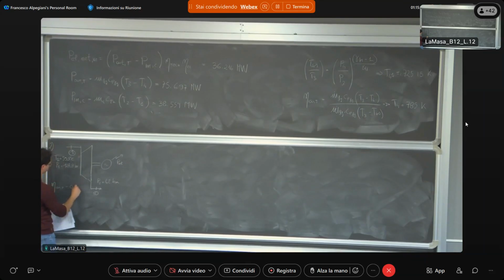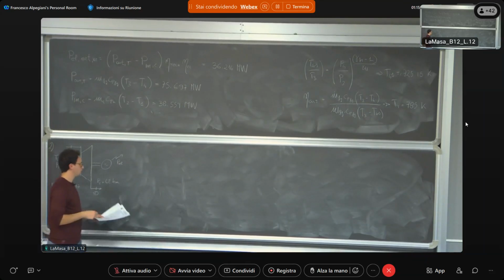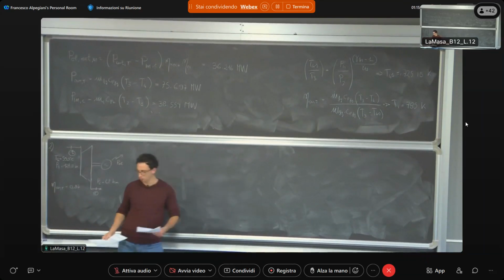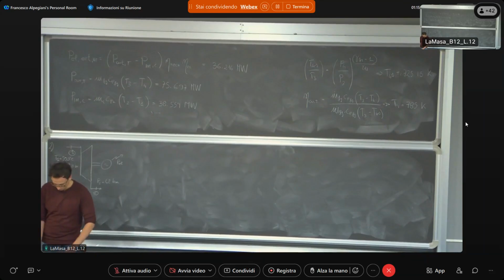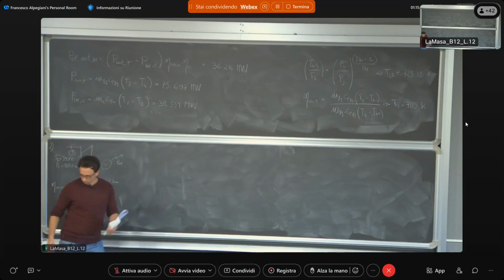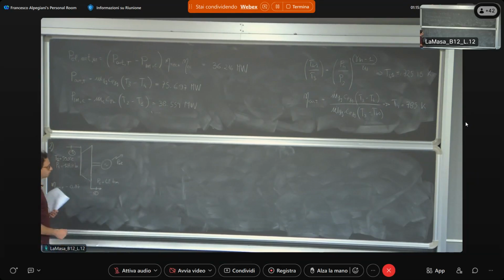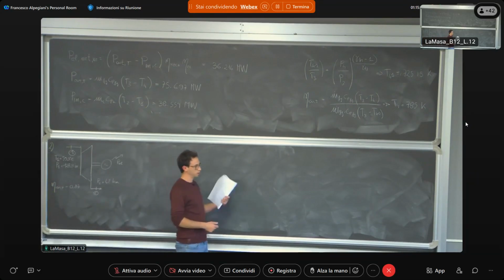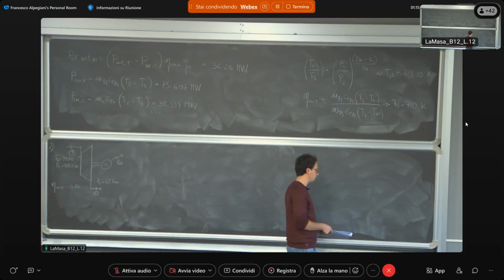It is equal to 0.87. So in this case, differently from the previous exercise, we cannot consider the assumption of ideal gas anymore. For water, we have to use the Mollier chart and the tables that are also given as PDF in the dedicated course section, to derive the other thermodynamic properties related to the stream, which are essentially the enthalpy and the entropy.